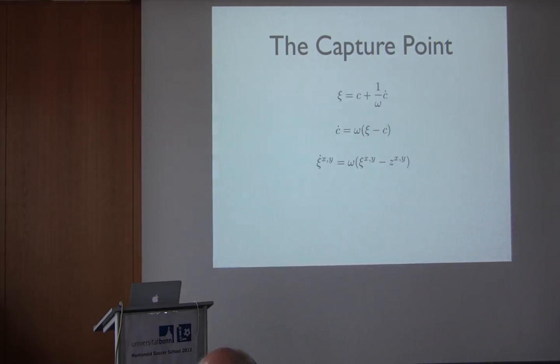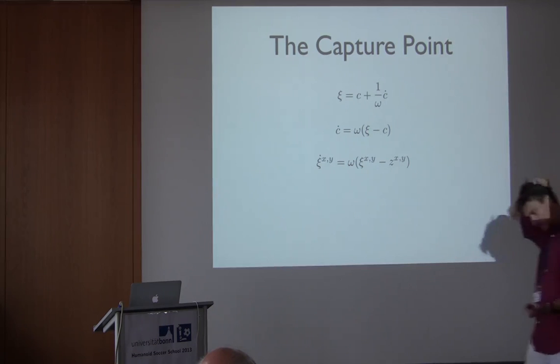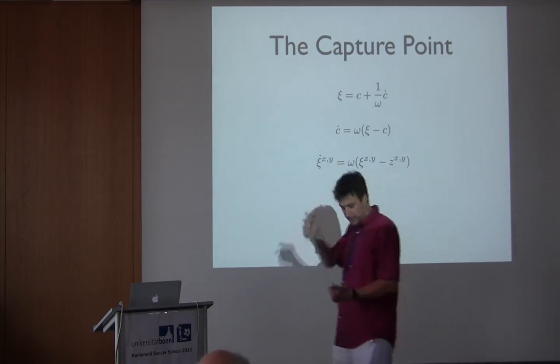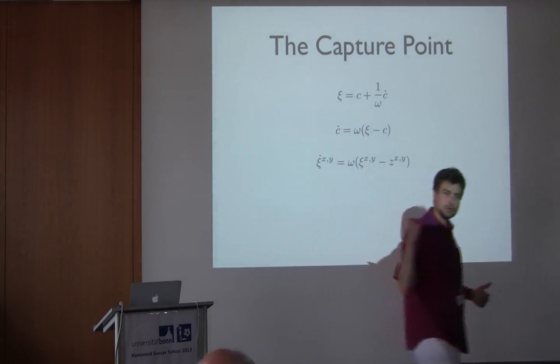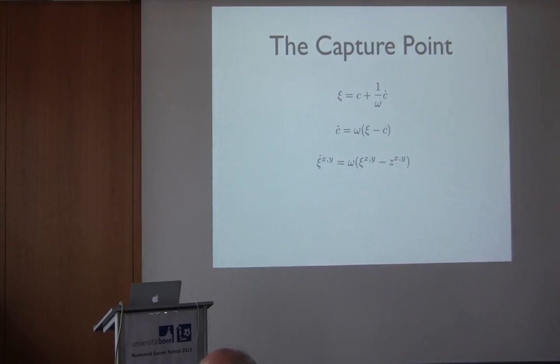So the problem is absolutely not to have dynamic motion. This is dynamic walking. The problem is related to actuators: they use position control motors, not force control, so this means they have very bad constraints on how dynamic your motion can be.